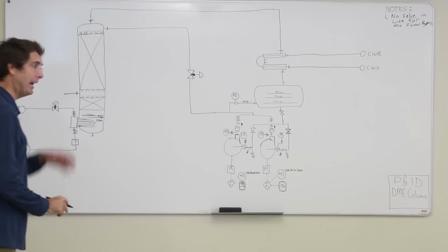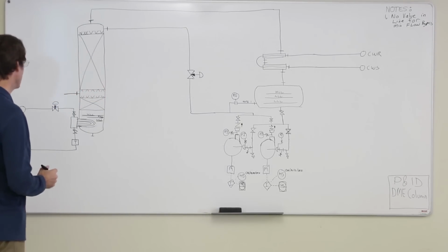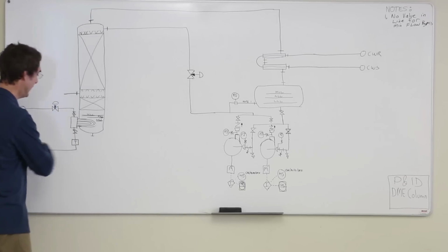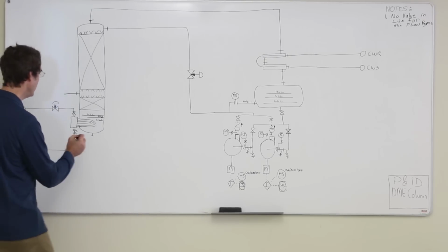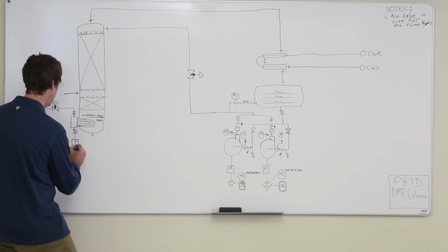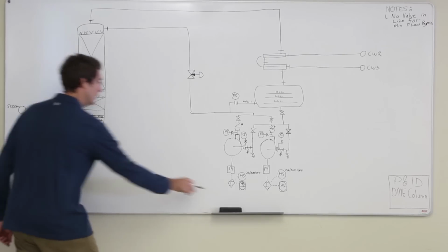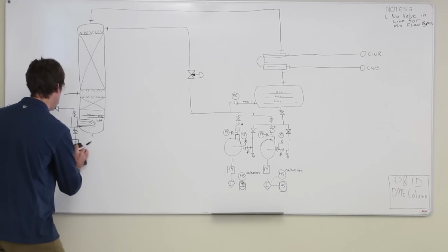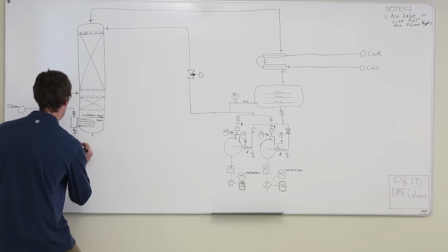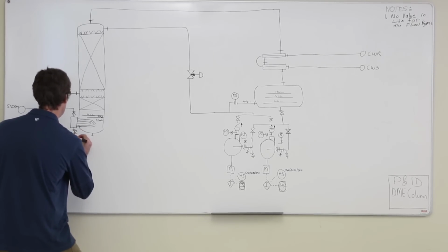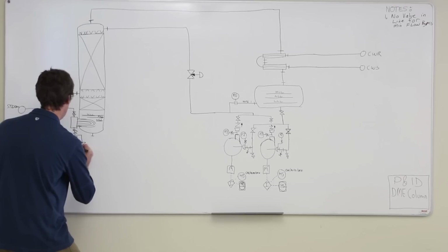Some steam traps also vent air as well. If you get a little bit of air in your steam system, you want to get rid of the air and pass it through the system. Typically, because steam traps are fraught with a lot of failures, they'll put a bypass around the steam trap, maybe like this, so that you can operate the piece of equipment.